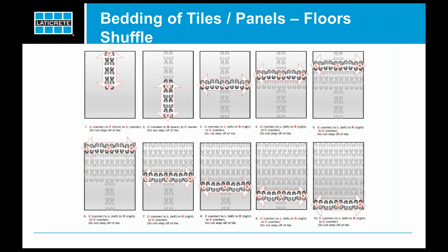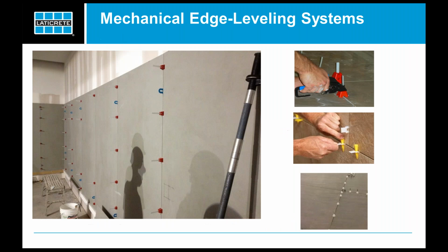One thing that it's important to note too is that labor, for these specifically gauge thin tiles, has taken a position that only 5.5 millimeter and thicker materials can be used on floors. Now, some manufacturers will allow you to use the 3 millimeter type on floors, but you have to follow their installation practices specifically to make sure that it's going to work correctly. But in most cases, labor has taken a position that only 5.5 millimeter in thickness should be used on floors.